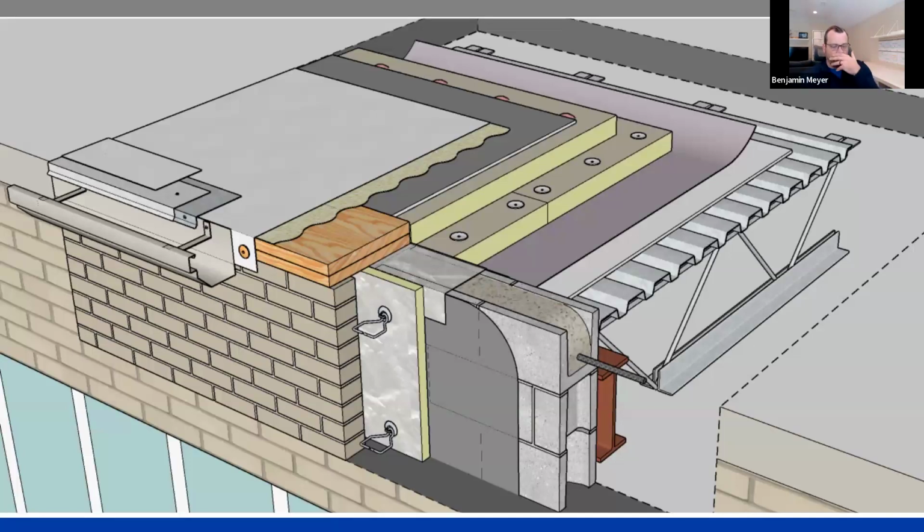So what do you see on the wall, Herman? I'll let you start us up the wall, and I'll take it to the roof. Well, as we take a look at our condition, if we start at the base of the wall and work our way up, we've got a masonry wall with our brick ties. So obviously there are some concerns with thermal bridging. You've got to take it into account. We're punching holes in our insulation, so we need to make sure the installation is done well. We've got our weather barrier over some concrete block, as we make our way up.